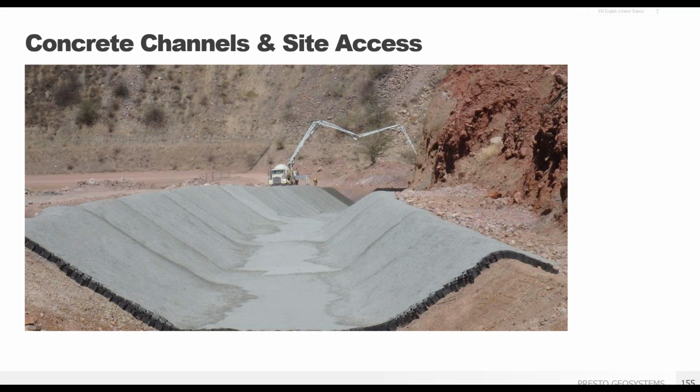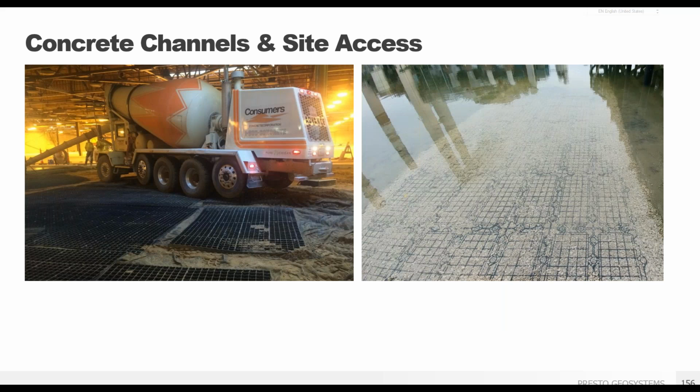And a pro tip for concrete channel infill is to use a concrete boom pump, as you see here, or a line pump if you have an install that's easily accessed horizontally. Another important consideration and technique tip is to include site access along the channel crest that can support the loading of cement trucks and other heavy equipment. Temporary access mats can help if design constraints will not permit access as part of your design, and can even be placed in water.